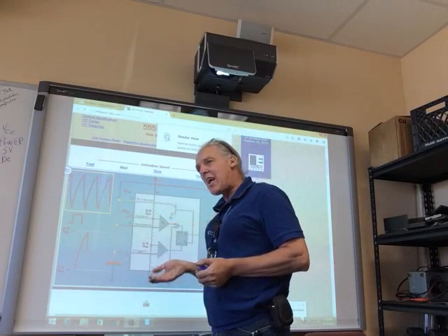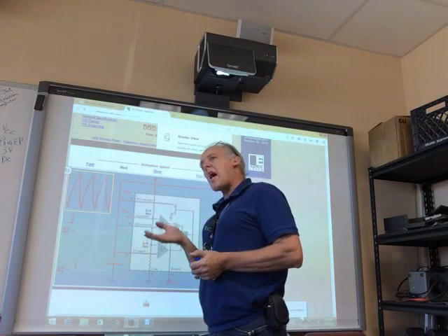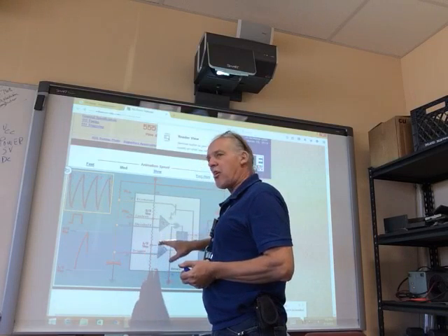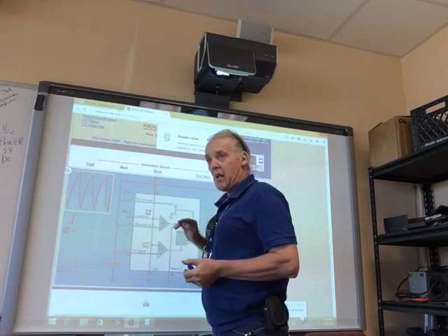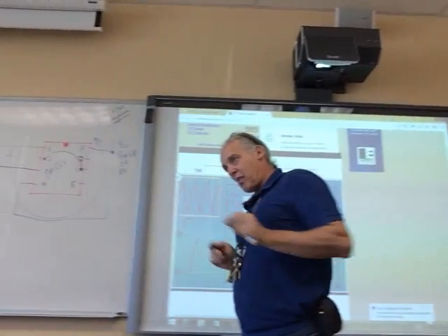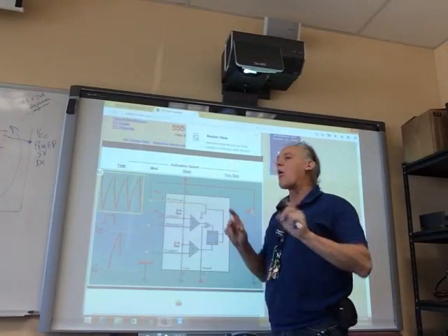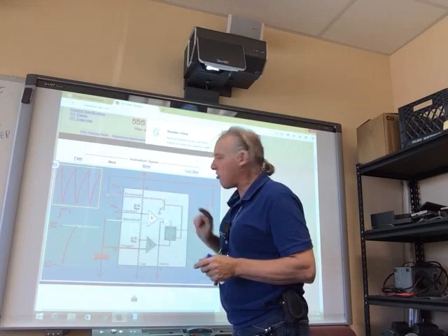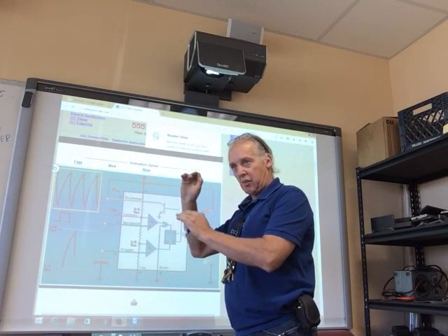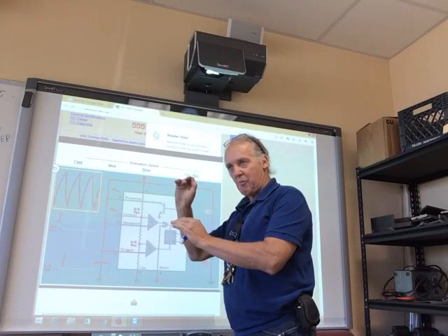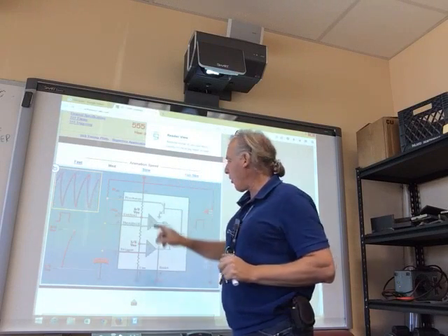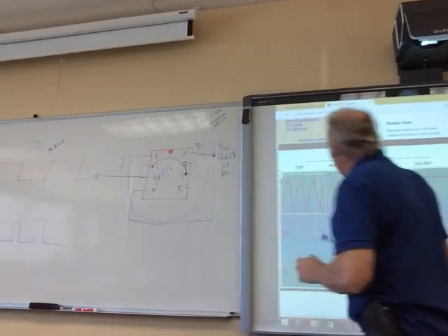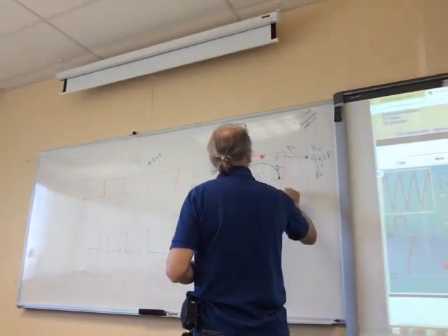Now we can change that up or down linearly and change the control, which will set this so it will do other things, okay? In other words, we can generate other sawtooths and things like that, okay? We're not going to. We're just going to leave it the way it is because that voltage divider right there, those three resistors, will keep it in sync. It'll keep it so it's oscillating a square wave, okay? Make sense? Another example of where voltage dividers operate well, okay? All right, so we're not going to worry about pin 5. So I always just put an X there.